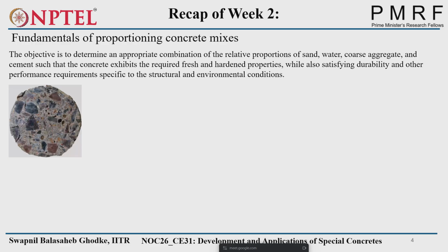According to Indian standard codes, we design the mix. Designing the concrete mix gives us the proportions of everything, like sand, cement, fly ash, and silica fume, or any supplementary cementitious material. We can't take any arbitrary proportion and prepare the concrete mix. We have to design the mix according to the code.